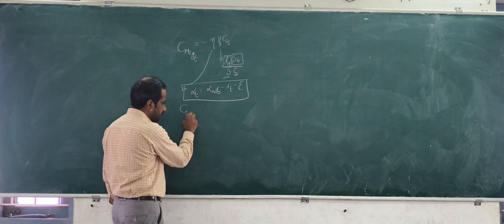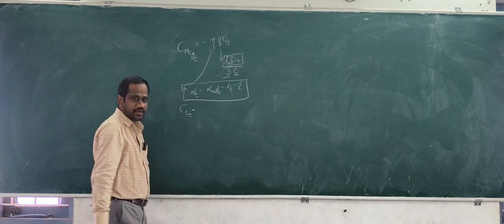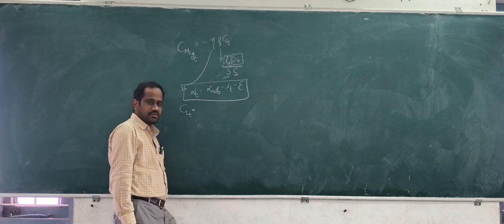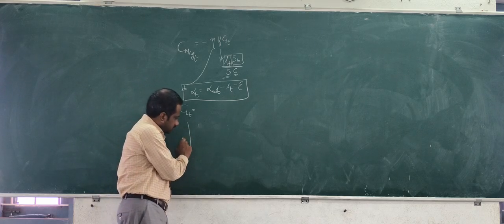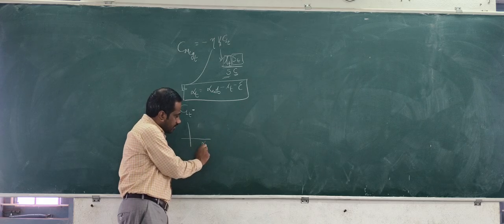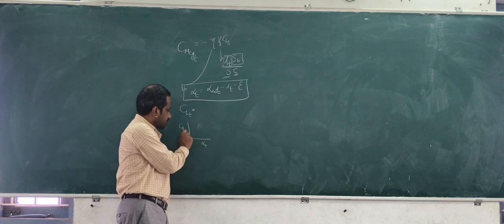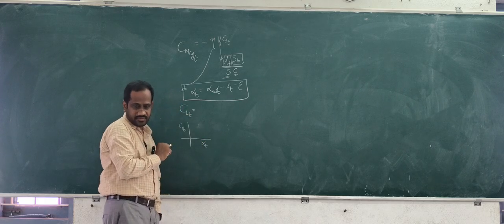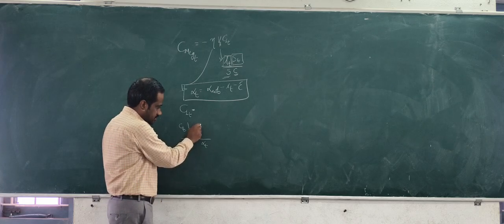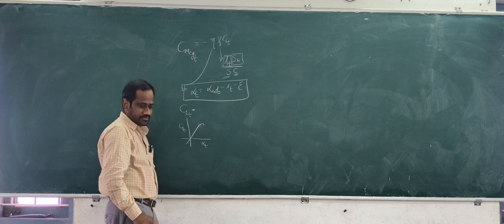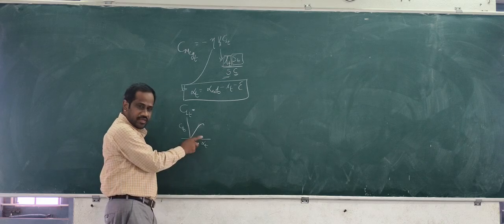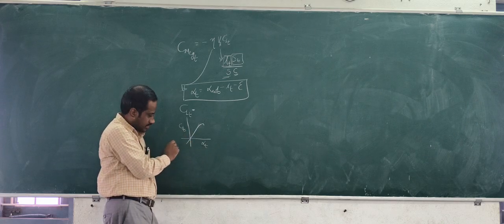CLT can be written, in a general sense, from the alpha t versus CLT. How else can we write this CLT from the lift curve? Just imagine. We are trying to write in different formats. What is the slope of the lift curve of the tail?